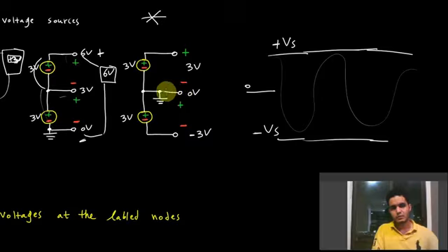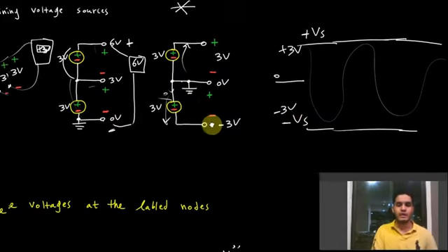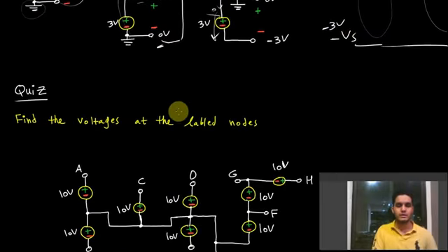So if you have equal voltage supplies, you would have the positive terminal at ground for one of them and the negative terminal at the other side, and you would measure negative 3 volts here, because you're going from 0 volts, dropping 3 volts, and you measure negative 3 volts. Now if you start from ground and you go up, you have a rise of 3 volts, and you measure 3 volts there, so plus 3 volts here and minus 3 volts down there.